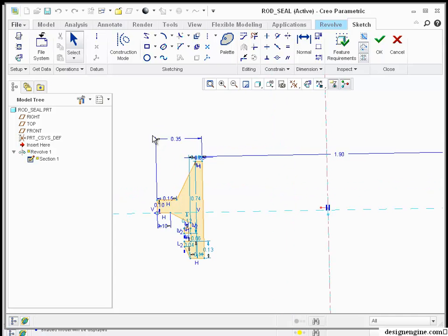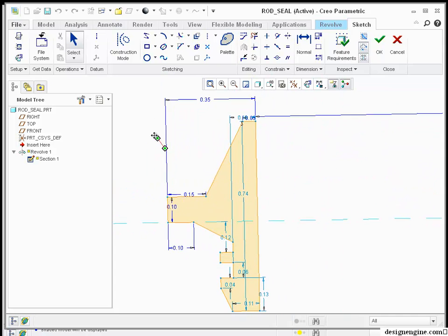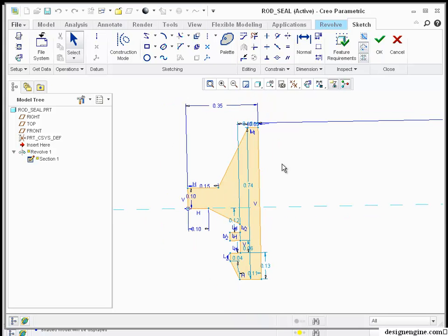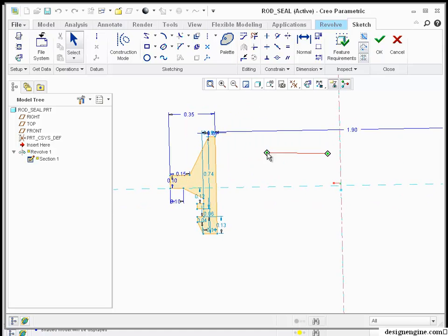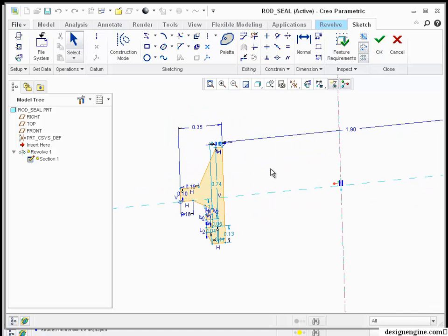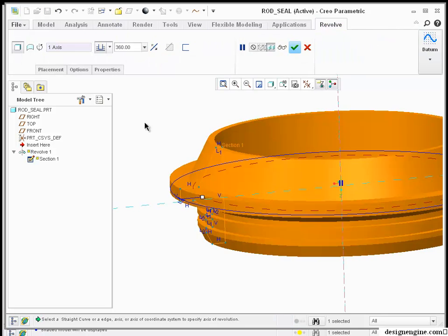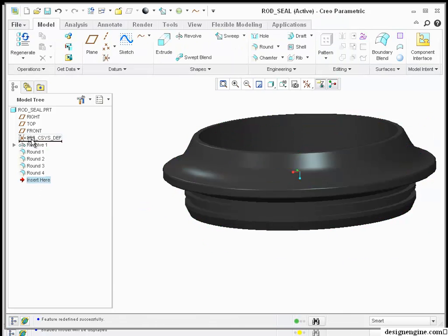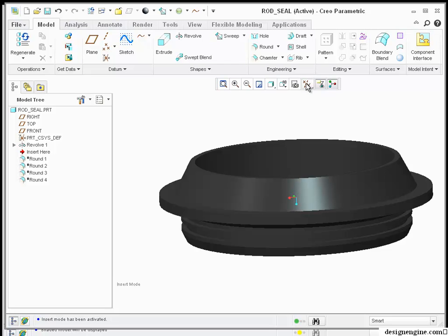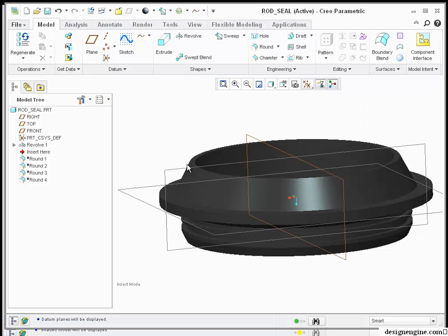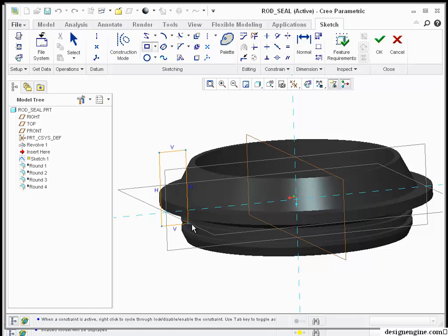I would have probably built the same geometry using underlying curve geometry because then I can stack up these underlying curves to help me leverage the parent-child constraints in ProEngineer. To illustrate that as an example, what I'm going to do is go to insert mode up here, turn on my datum planes, and sketch a box geometry on this plane.